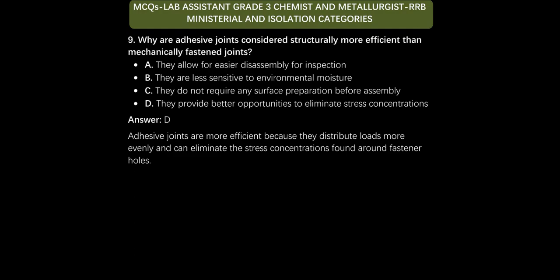Why are adhesive joints considered structurally more efficient than mechanically fastened joints? Option D. They provide better opportunities to eliminate stress concentration.